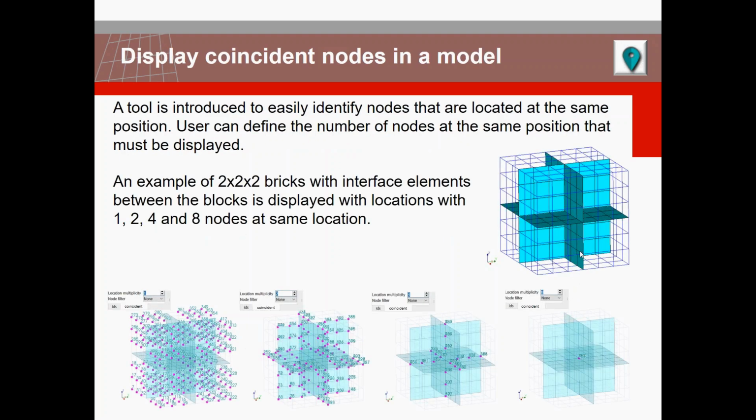Moving forward, this tool can be used to identify the co-located points. So if you have a model and you have some discontinuity in the model due to the definition of an interface or a fault, or maybe you just split it and introduce discontinuity between different parts, you can easily identify this discontinuity by means of coincident nodes in the model at the mesh level.